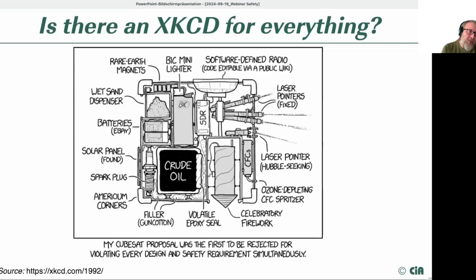So the next question I have seen is, since almost all drive solutions rely on classical CAN, are there any activities regarding bringing classical CAN to a stage where SIL 3 at a reasonable update rate can be reached, or are the activities of CiA only related to CAN XL? We have CiA 402, which has additions for CANopen Safety, so that functionally safe drives can be implemented. So for CANopen Safety, it has additions in there. We have updated it for some time now.